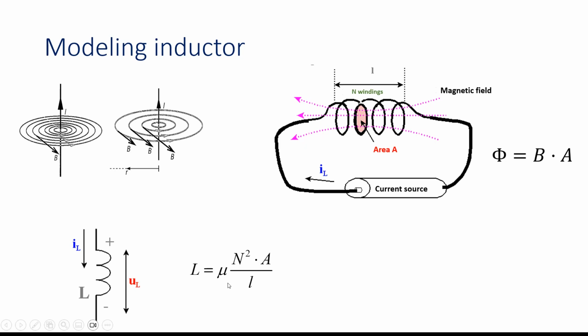So it's equal to the degree to which the material conducts magnetic field lines. Because the magnetic permeability of iron, for example, is greater than that of air, the housing of the solenoid is often made of iron, and the flux is also equal to the self-inductance L times the current through the coil. So it's L times I, or L times I_R in this case.